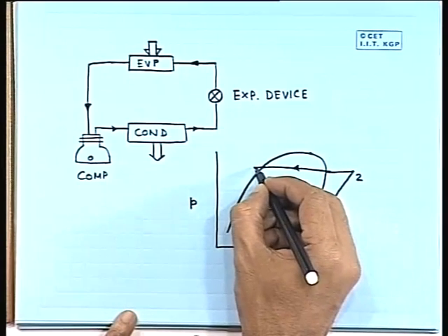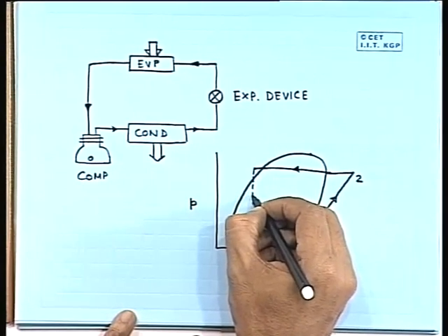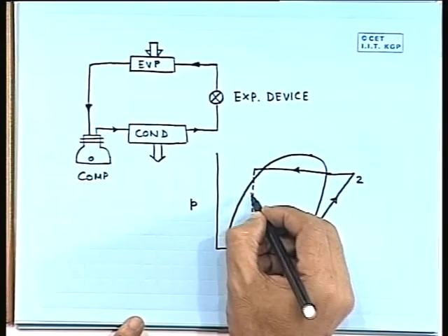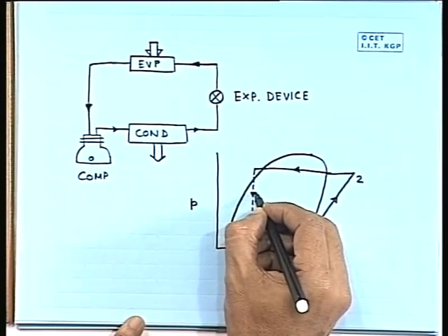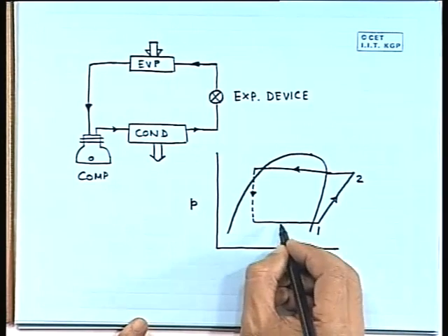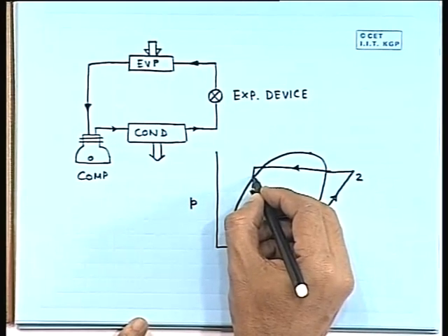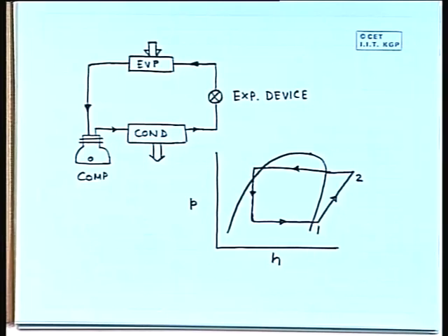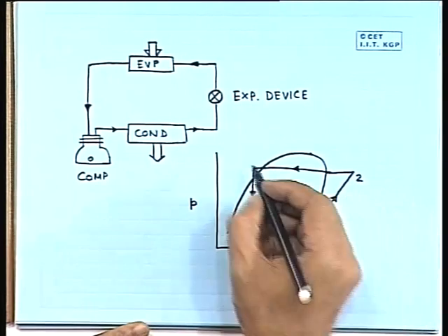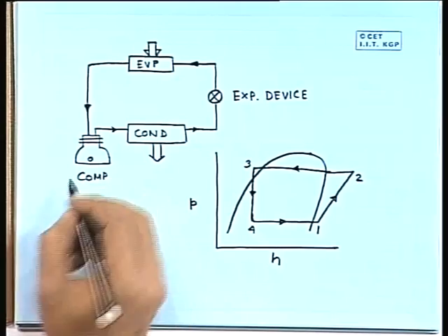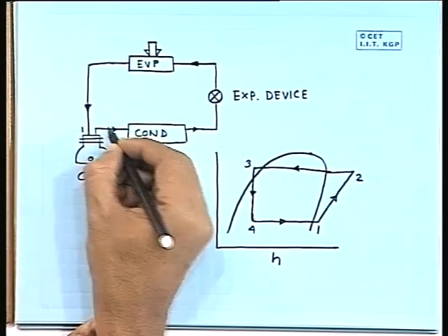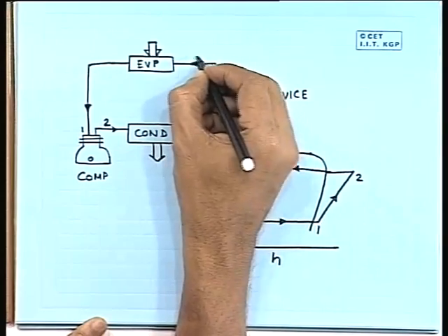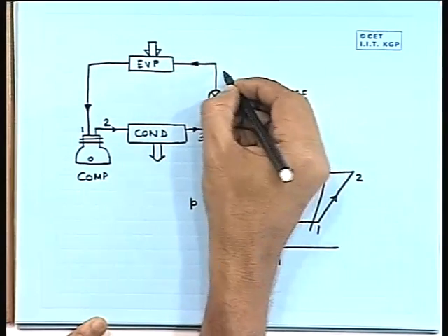Then we will have the Joule-Thomson expansion process, which is irreversible, and we can express it with a dotted line, but in most cases it is shown by a firm line because we assume that it is along this constant enthalpy path. So, 1, 2, 3 and 4, and here also you will have 1, 2, then 3, then after expansion this is 4.